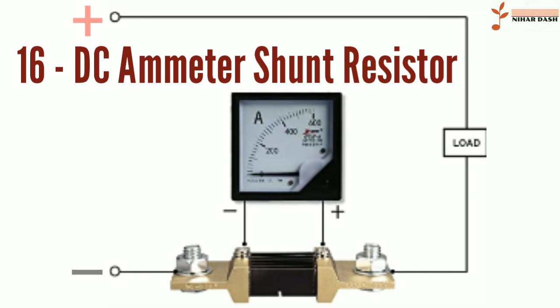A typical shunt consists of 2 solid metal blocks, sometimes brass, mounted on an insulating base. Between the blocks, and soldered or brazed to them, are 1 or more strips of low temperature coefficient of resistance, TCR, manganese alloy. Large bolts threaded into the blocks make the current connections, while much smaller screws provide voltmeter connections. Shunts are rated by full-scale current and often have a voltage drop of 50 mV at rated current. Such meters are adapted to the shunt full current rating by using an appropriately marked dial face. No change need be made to the other parts of the meter.